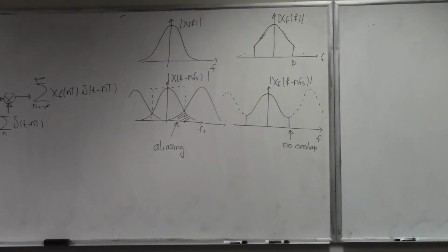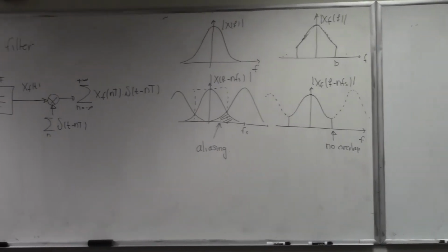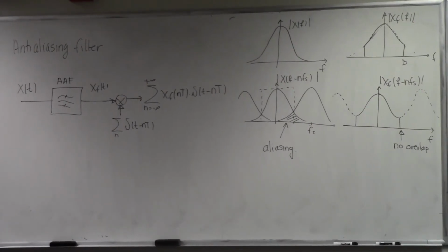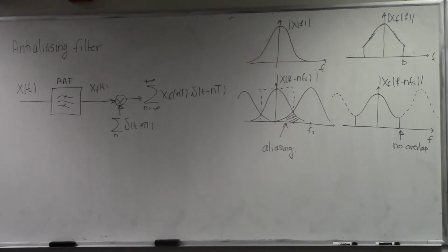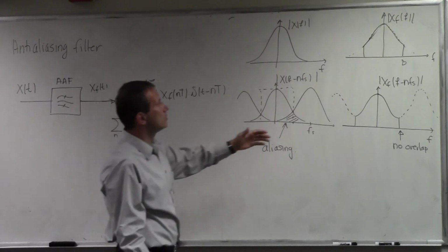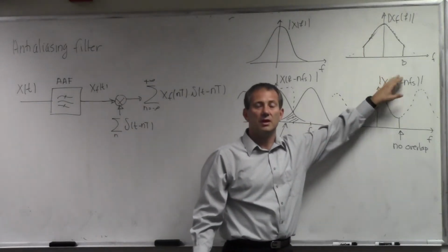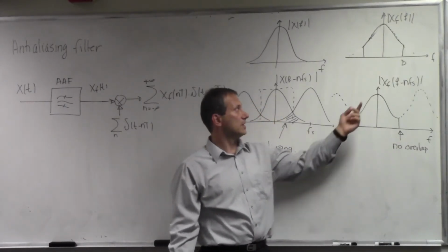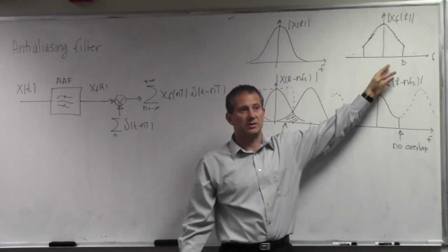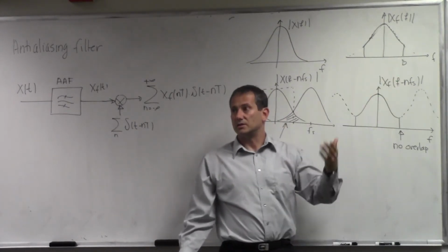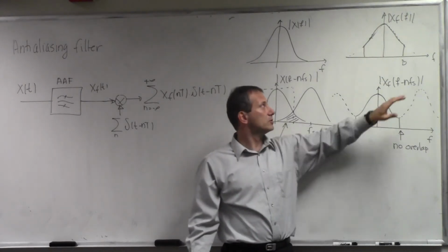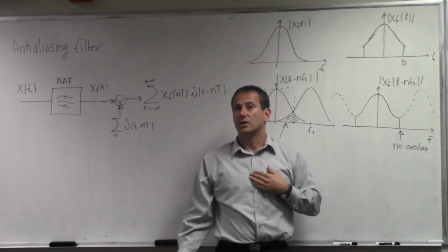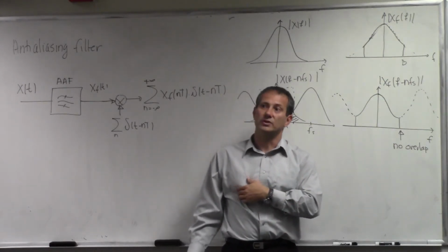So that's what we always do. As a result of this process, however, the signal is distorted, right? Because we're getting rid of some of the signal components, and as a result, the signal is not the same as it was, right? But that's the bad news. The good news, it's completely within our control. We are the ones controlling how large the B is, and depending on a particular application, we can make it larger or smaller. If it really bothers us and whatever is distorted as a result of this low-pass filtering is significant, then it's within our power usually to change this and make it larger, and then therefore get a signal that is closer to the original signal.